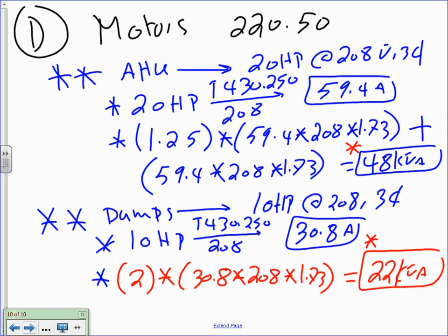Okay. Let me repeat myself because that could be confusing. When we did it in the Excel sheet, first we added them, and then we took the largest motor and added 25% on it. But you can do it this way. What I did here in the calculation, I took the first motor, the largest motor. Everybody can see that factor for the largest motor. So I took this multiplied by the largest of the two motors, and then I added the second one to it. Then I added the two pumps together. Now I'm going to add the total for the whole step, all of them together.